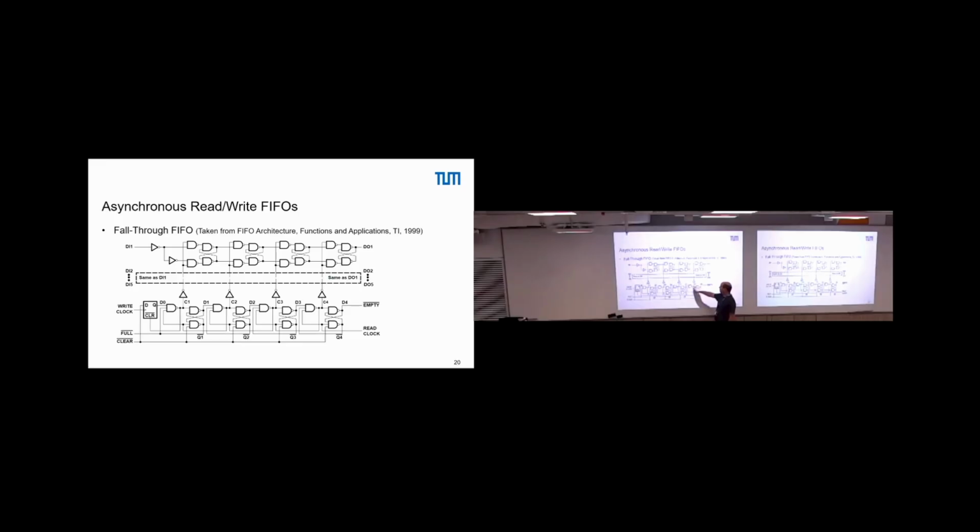So you need to ensure that the spike that you have here is long enough, but not so long that maybe this one here is still enabled when you write the next one. Otherwise you overwrite several of the data words, which you don't want. So it's at least a semi-custom design where you have a lot of handwork to do. That's another problem here.